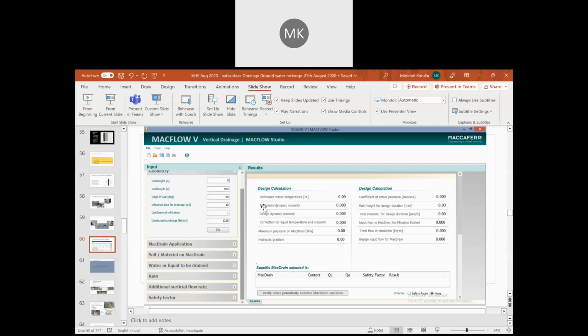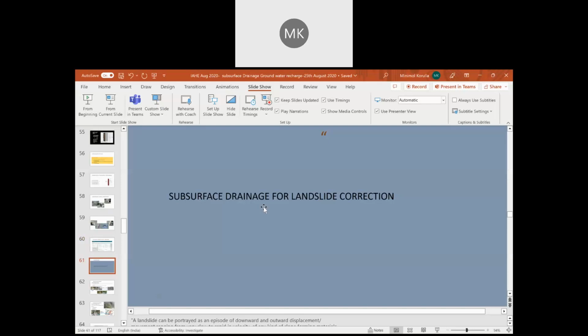And if you are going about the aggregate type, whether it has to be metal or crushed rock or river rock, it honestly depends on the type of the project. If it is a very important project, we have to go as per the gradation, but it is defined in MORTH 700 or IRC SP 59, and most importantly IRC SP 42.